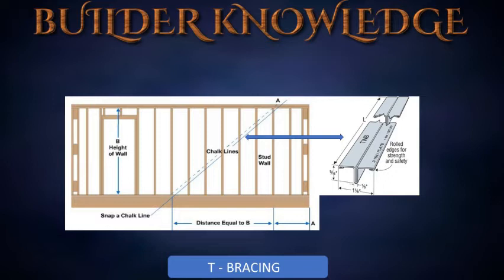Lay out the bracing where you want it to go and draw a line on the structure, and then come back with a circular saw, cut into the wood, and then place the bracing into the wood. Only place nails in the top plate and bottom plate.